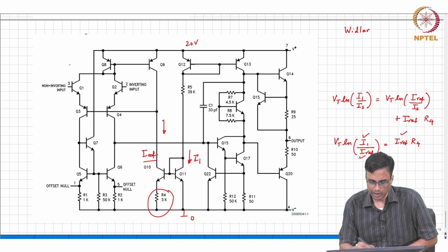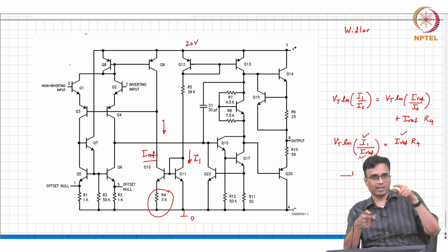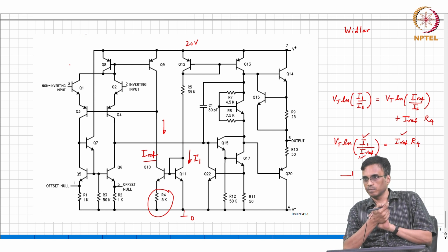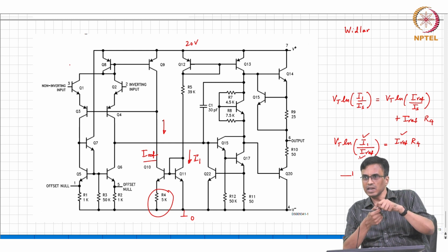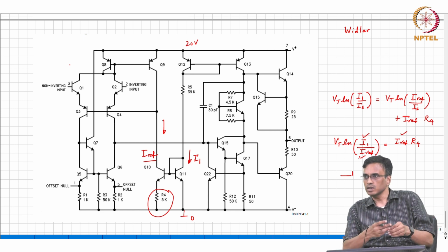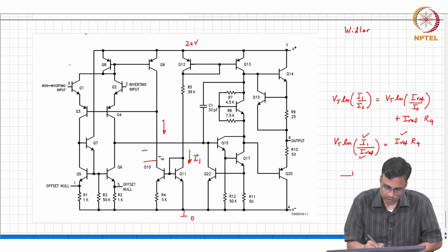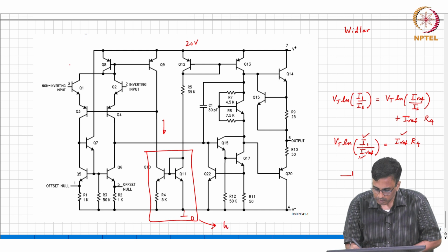right. So, normally if you have some voltage and want to generate a current, you have to do V by R as the current. So, if you want a very small current, that resistance must be very large. Okay, it turns out that large resistors are difficult to make on an IC. So, basically you wanted to get a very small current, but with a small resistor. So, this is one way, this is what this current source is called, the Widlar current source.